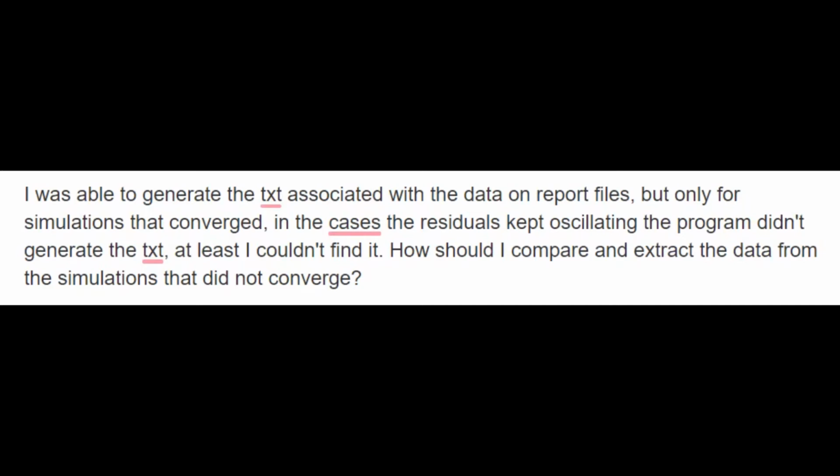calculating the progress of the solution. From a mathematical point of view, it's interesting, but it has absolutely no relation to the physical changes in the flow from one iteration to another. It's absolutely useless from the physical point of view. It has interest only from the mathematical point of view. But in the case of transient, it is the physics you are simulating from one time step to another, and then the creation of animation is interesting.